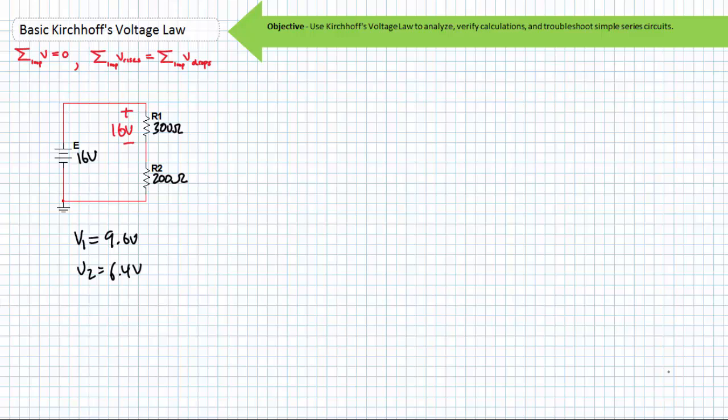Here's where we must necessarily place a fork in the road. What if your subsequent check of the voltage drop across R2 yielded 0 volts? What if your subsequent check of the voltage drop across R2 yielded 16 volts? These are two totally different, totally wrong creative interpretations of the circuit you're intending to build.